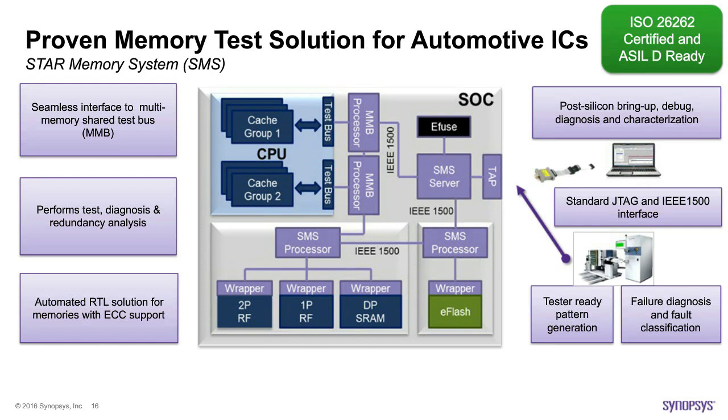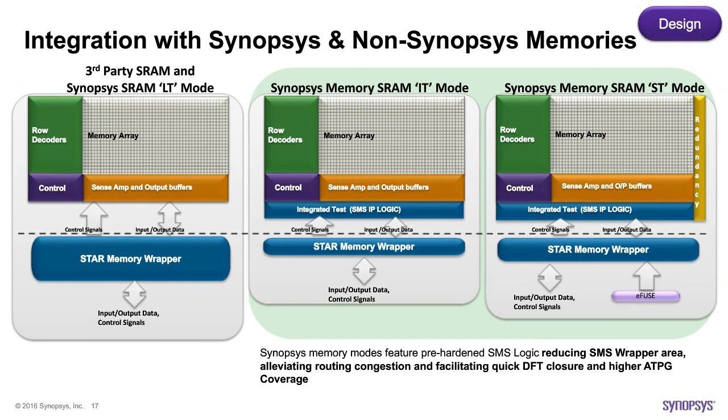Now, what we build here is not only at the design stage. We also need to provide the post-silicon capabilities, and what Synopsys provides as STAR Memory System does that. So on one hand, it's an IP that gets incorporated in the chip, inserted, verified, and then post-silicon analyzed for silicon debugging and volume testing purposes. Now, all of that is meant for any memory. And today there are many SoCs with different sources of memories that use this STAR Memory System.